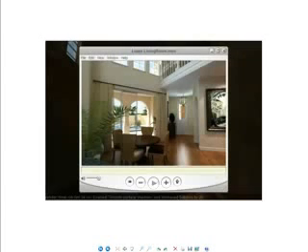So I'm finally ready to start adding light planes to all of these openings. And basically anywhere outside light can come in, that's where I want to add these VRay light planes. The very first consideration I need to make is whether to place the lights just inside or just outside these openings. And what determines that is whether or not there's any objects that would interfere with the lights. I know that I can't allow any objects to intersect or touch the VRay light plane, because it can cause erratic lighting. So if there's any objects just inside these openings, such as curtains or drapes or any furniture, I might need to place the light outside.